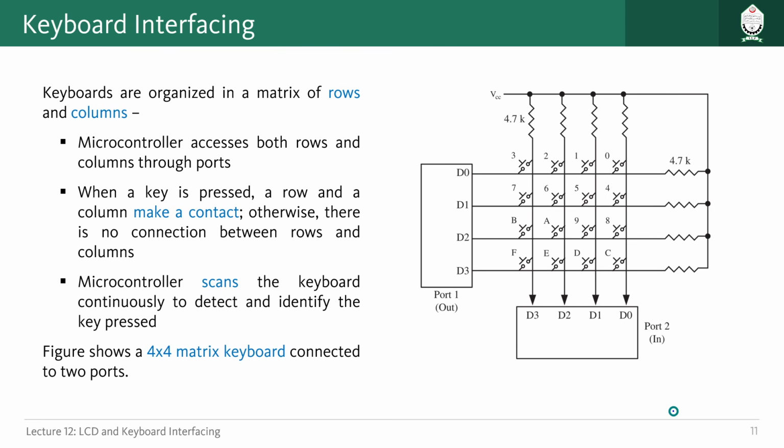keyboard interfacing. To understand keyboard interfacing with 8051, first of all, we have to understand how internally these things are built. So here we have one example of a 4x4 matrix keyboard. Here you can see we have 16 different push buttons connected with each other in a specific manner. If we look at one push button here, you will see that we have two contacts, and whenever you press the button, these two contacts are connected with each other, otherwise they are open, right?